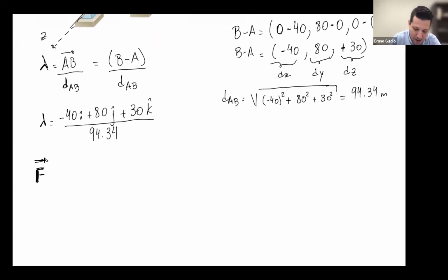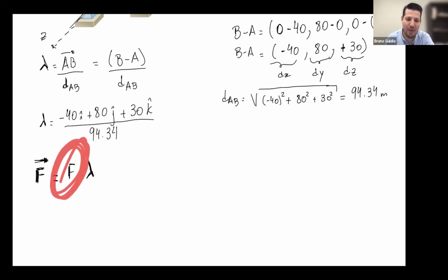When I'm not only trying to find lambda, I'm trying to find the force vector. And what is the force vector? F times lambda. Guys, please pay attention. Once we start having more and more vectors, the most common mistake that I see from students is forgetting about this F, forgetting about the magnitude of the force, and working only with the lambda.